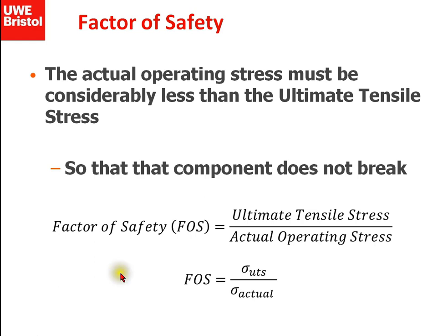Because this is the largest amount of stress that a sample can take, most structural engineers will use this as the value to measure the factor of safety. So we're going to be using the ultimate tensile stress as a means for factor of safety.